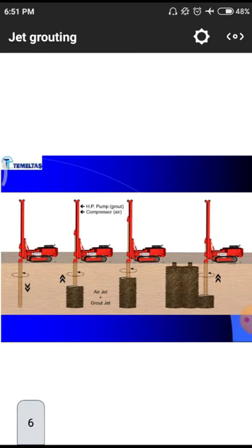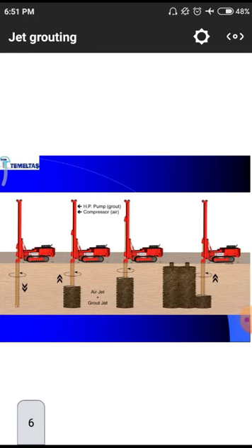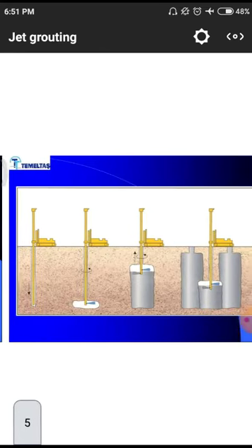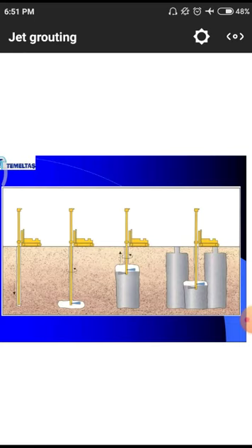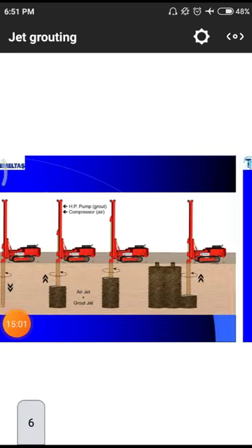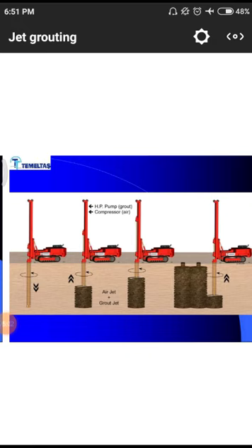This is also a simple process, the same as the previous one. The process is the same, but the blades are different. Here, only a single blade with a straight portion is there. But here we have to observe that two pipes are utilized. The two pipes create two suction holes. Into the suction holes they inject two blades, which remove the material. After a few hours, the total material will be replaced with this jet grouting material.